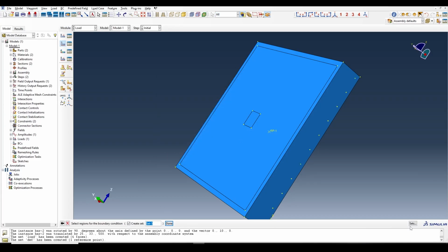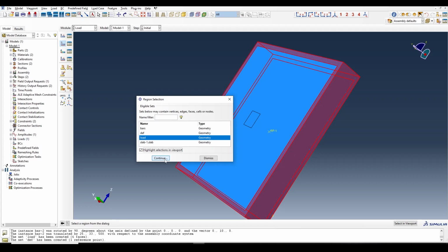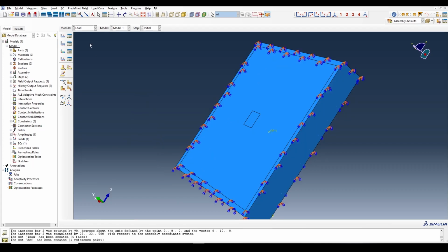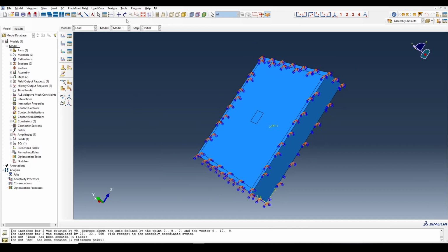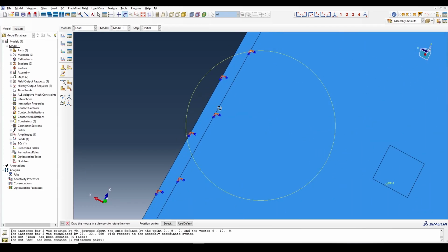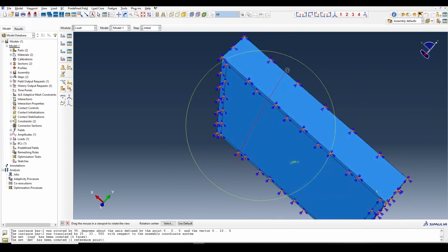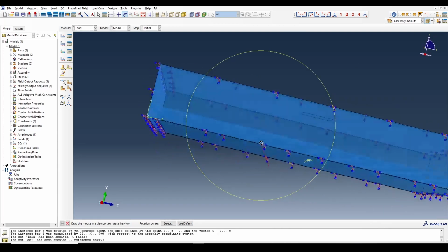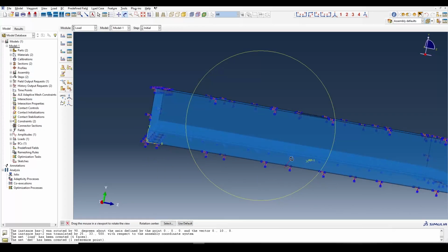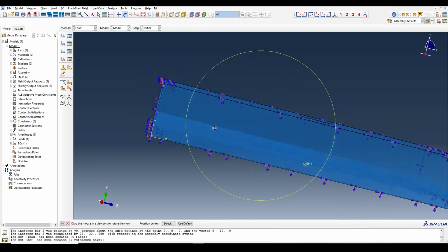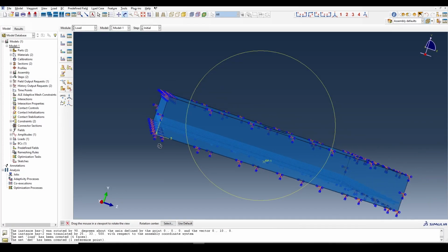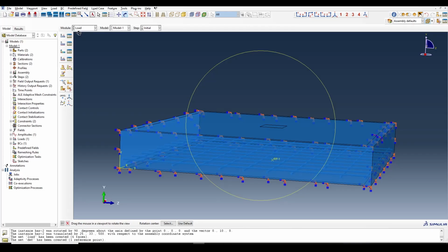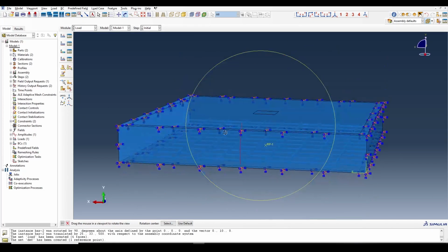Symmetry, we have already created a set named as load. Okay, we fixed that ends. You can now see that up to this distance, the top surface and bottom surface are fixed. So to avoid any local failure, you can see the bars after the bars are embedded in this support to avoid any local failure. Similar thing we can do in these four faces also.